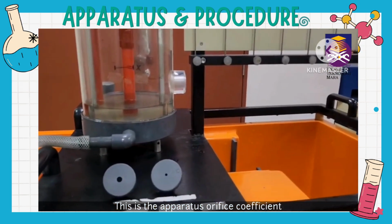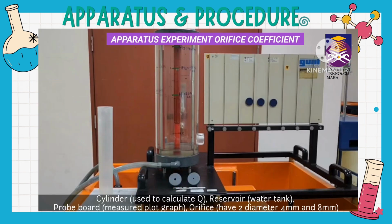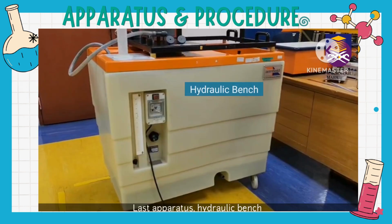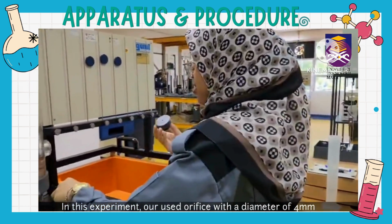This is the apparatus for the orifice coefficient experiment: a cylinder used to calculate Q, a receiver, a water tank, a probe to measure and plot the graph, and orifices of two diameters, 4 mm and 8 mm. The last apparatus is the hydraulic bench. In this experiment, I will use the orifice with a diameter of 4 mm.